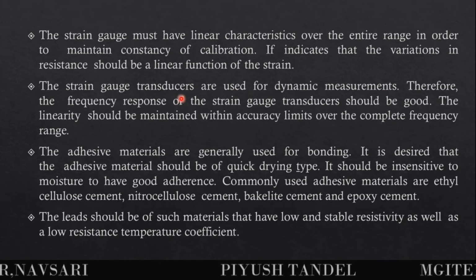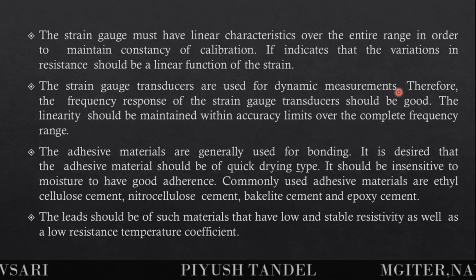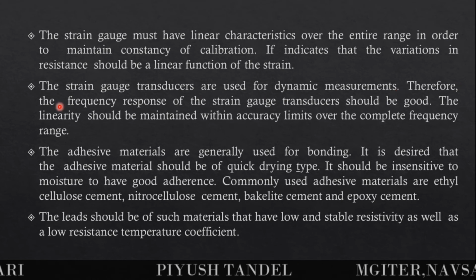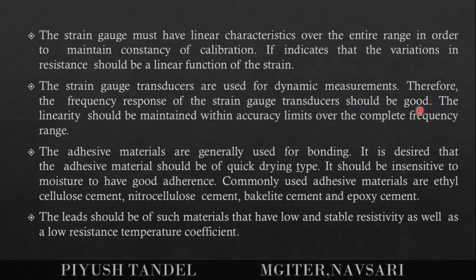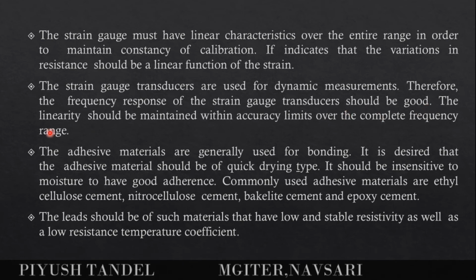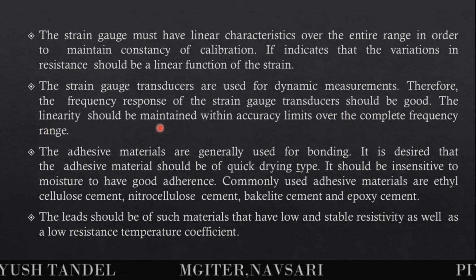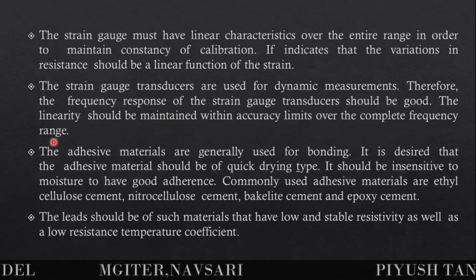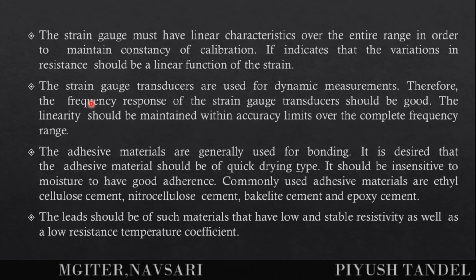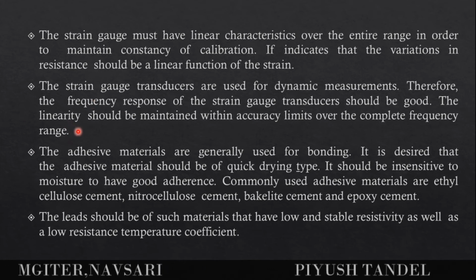Then after, strain gauge transducers are used for dynamic measurement. Okay, strain gauge transducers are used for dynamic measurement. Therefore the frequency response of the strain gauge transducer should be very high, and good. The linearity should be maintained within the accuracy limit over the complete frequency range, and we are going to measure the dynamic characteristics with the help of the strain gauge.